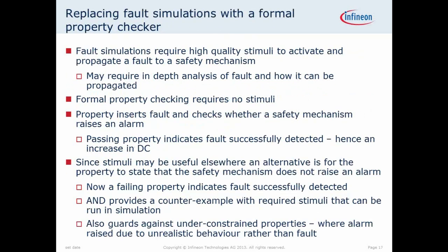Okay, so the third strand of what we did was to try to replace the fault simulations, which are extremely time-consuming and quite effort-intensive, with a formal property checker. Fault simulations require high-quantity stimuli, as I said, to activate and propagate the fault to a safety mechanism.